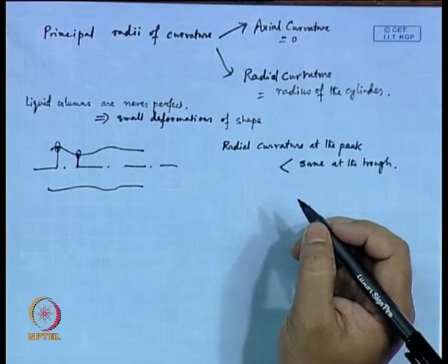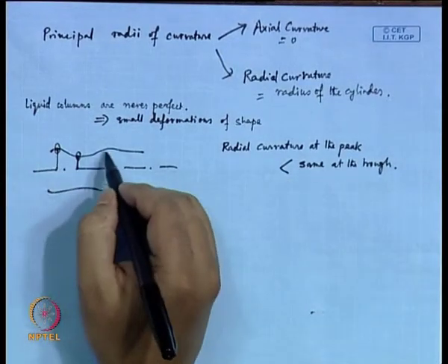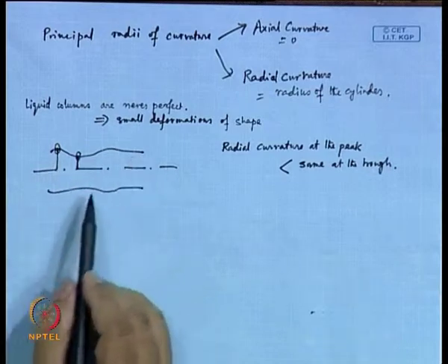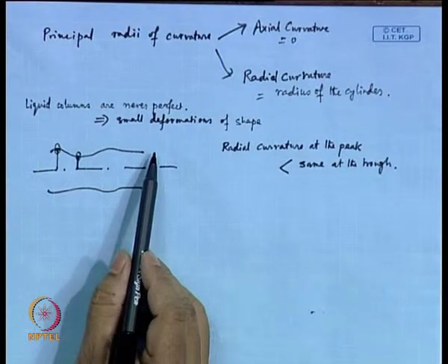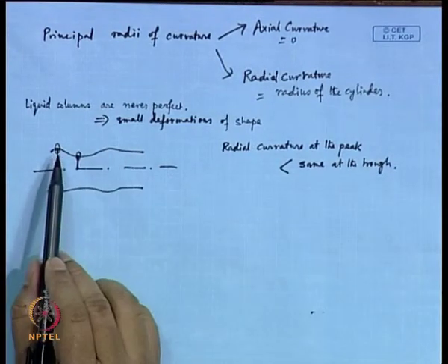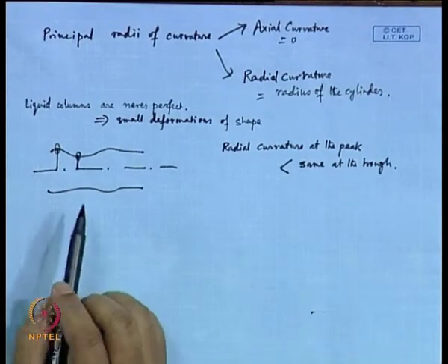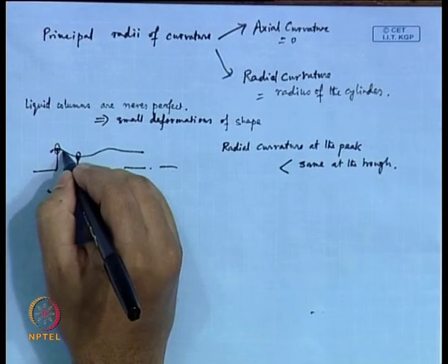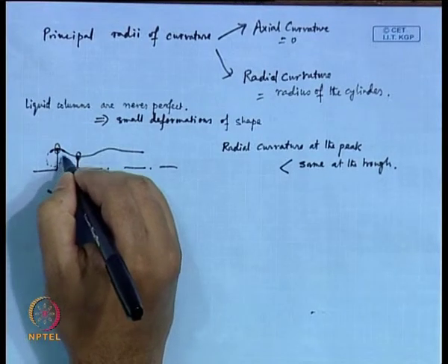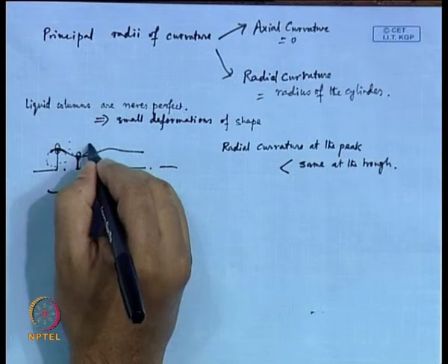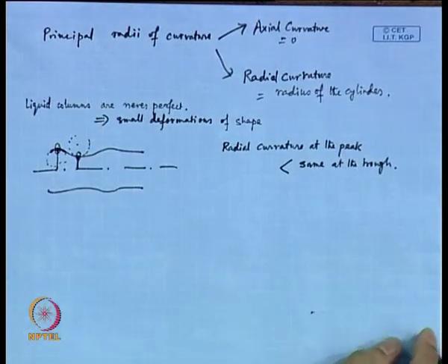And if somebody tries to find out, there would be an axial curvature being generated because of this modulation. Earlier, when you had a cylinder, there was no axial curvature, it was all straight. So, you considered the axial curvature to be 0, the radius of curvature being infinity. But now, since there is an undulation, there would be an axial curvature present. To find it, you need to draw a circle and find the tangent. Here the center of the circle would be outside the cylinder. Okay.